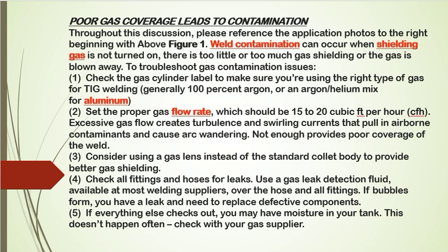If everything else checks out, you may have moisture in your tank. This does not happen often. Check your gas supply. Okay. So this is the first mistake: poor gas coverage with contamination.